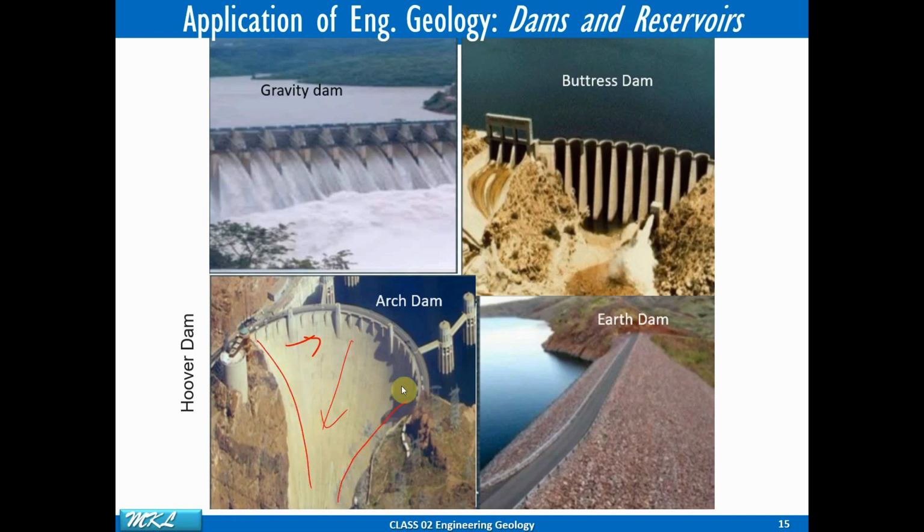There you will see that in the past people built a dam, this arch type of structure, but they didn't consider the geological formation here and here. So this geology is very much important. This surrounding geology is very much important because the dam structure is held by these structures, these geological rock types.